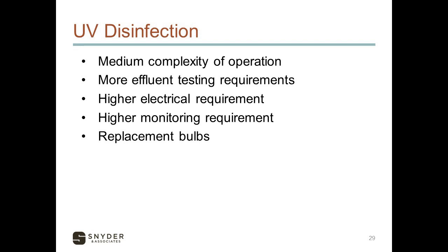It does require some effluent testing as well as a pretty high electrical requirement for those lights, higher monitoring requirement to make sure it's operating properly each day, and then a maintenance cost of replacing the bulbs on a regular schedule. The good news is you don't need to run these through the winter months, and so you can just pull the bulbs and leave them inactive, depending on your permit through the winter months.